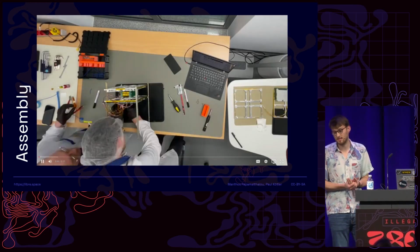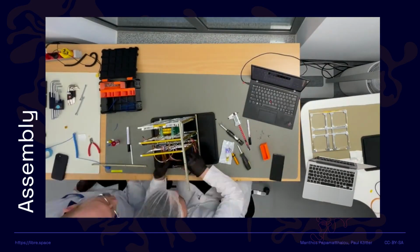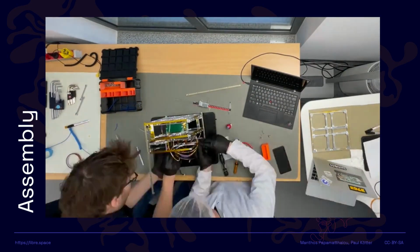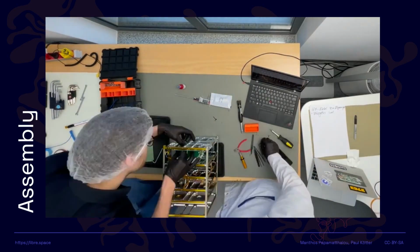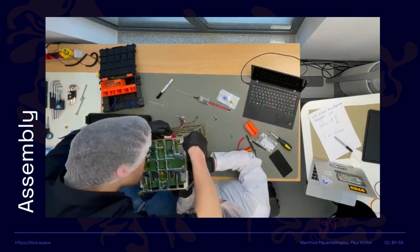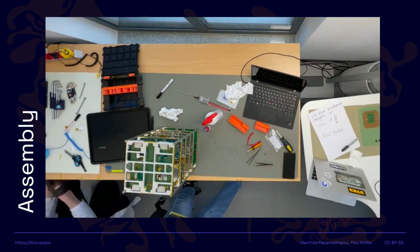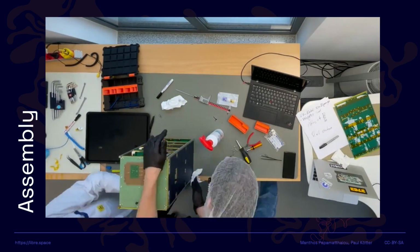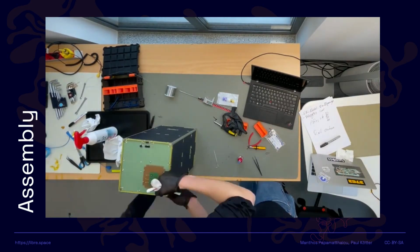And then you have all the devices that you need, and you need to go into assembly. The one we've flown has more than 2,200 components: 460 mechanical components, and then roughly 1,000-something electrical components. A lot of harness, so a lot of wires as well. And the integration here takes a couple of hours when you're well prepared. As the last step, of course, the solar panels are attached to the side, and they are connected by pogo pins, so you don't need any cabling. This is a very, very nice way to connect your solar panels.